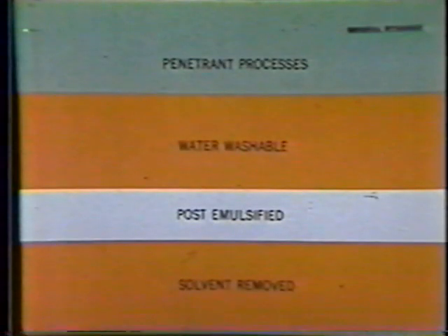A disadvantage is that conventional penetrants are easily washed from shallow discontinuities. Use of gel-forming or slow solubility penetrants minimizes this wash-away problem. The post-emulsified method adapts readily to high production testing, especially of large specimens. Emulsification, and therefore penetrant removal, is more easily controlled. There is less danger of washing penetrant from shallow cracks. Use of low-energy emulsifiers or hydrophilic scrubbers further improves sensitivity.